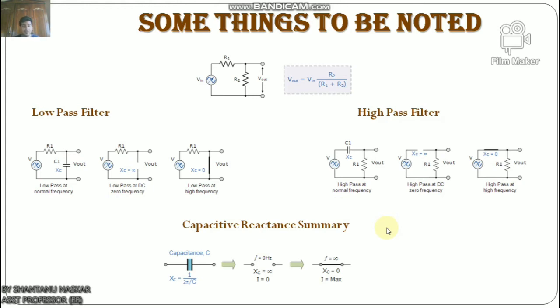The impedance of resistor R1 does not change with frequency. Resistors are of fixed value and are unaffected by frequency change. Then the voltage across resistor R1, and therefore the output voltage, is determined by the capacitive reactance of the capacitor at a given frequency. This results in a frequency dependent RC voltage divider circuit.